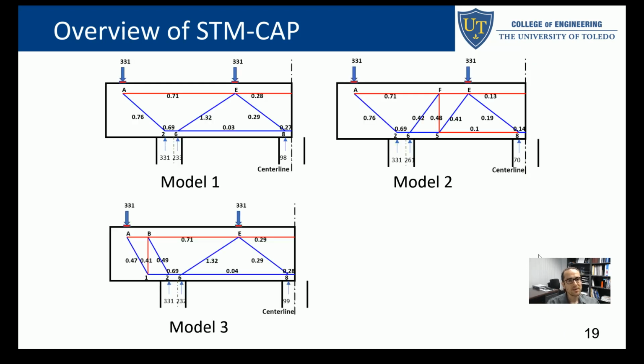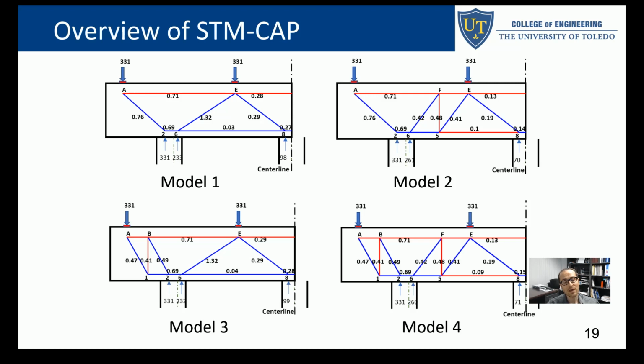You can see for this one you can create 4 different models using vertical ties or not. For example, this one, if you are not using vertical ties, you have an overload situation. So this member is 32% overloaded, so you should use the vertical tie. If the member does not have vertical ties, then that pier cap would be overloaded. So you need to rehabilitate it for shear, because that indicates a shear failure.